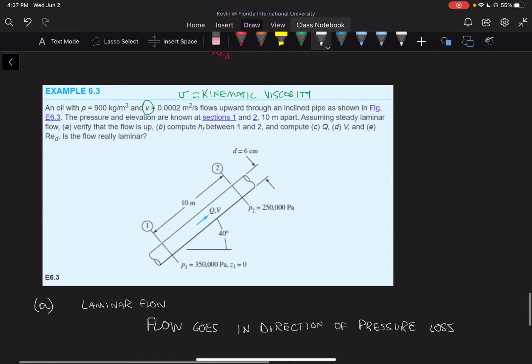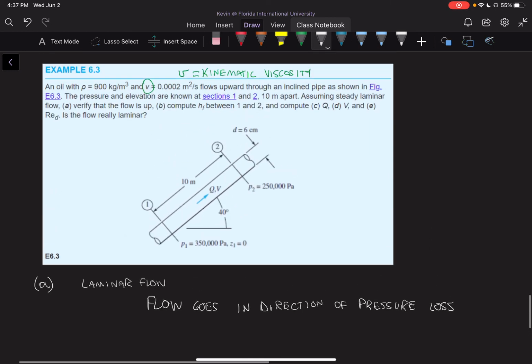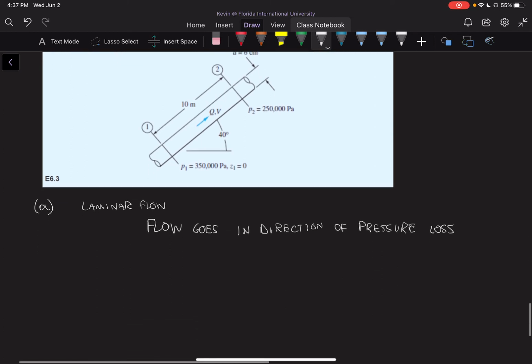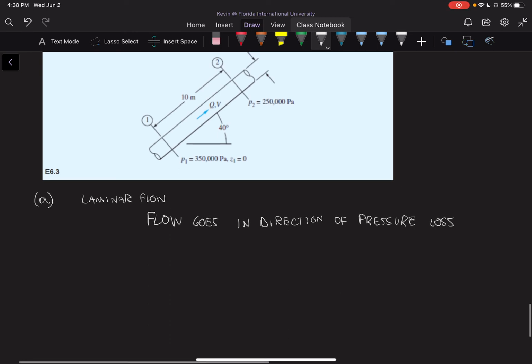And since we now have to take into account our friction, because we're looking at viscous flow in ducts and not inviscid flow in ducts, where we would just have Bernoulli's equation, we now have to come up with, so we have a straight pipe, and we now have to come up with an equation for this. So the equation we're going to use is our energy equation.